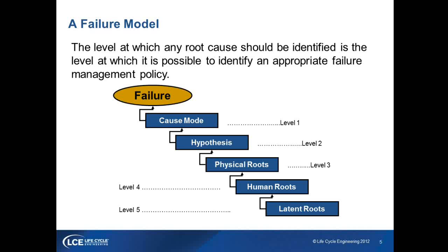Fine. So then I gather a team, I go through my process, all those types of things. But the question that I get oftentimes from clients is, how do I know if and when I've reached the root cause? So if you look at level 3 there, that's the physical root cause. So if it's a pump failure, maybe I have a shaft shear and break. I can take that shaft and send it off for analysis. That's my physical failure. Maybe it's a bearing problem that I can do some oil analysis and understand.